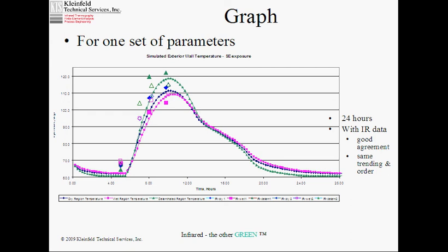The wet wall is the magenta, and you can see it has the least swing from nighttime, and this goes from 0 hours to, well, 4 in the next morning, 6 the next morning. But you can see at night, before the sun gets started, before the air temperature goes up, the wet area is the warmest, and during the day, the wet area is the coolest.